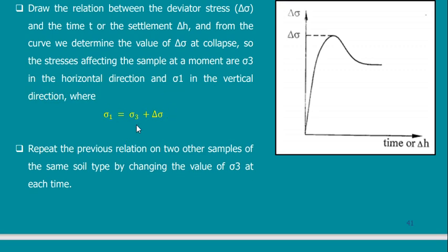You have to take into consideration that we said at the beginning that we have sigma 3, which is the water all around the sample. So it is coming from the sides, from top, from bottom. And then I started to add the stress on the piston. The stress on the piston is called delta sigma. So to get sigma 1, which is the vertical stress, it should be equal to what? It should be equal to sigma 3, because sigma 3 is horizontal and it is vertical also, it is there because water is pushing all around.